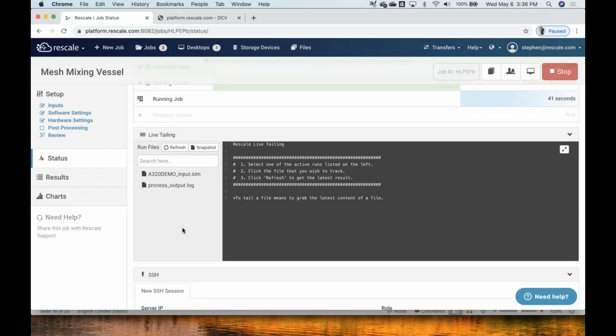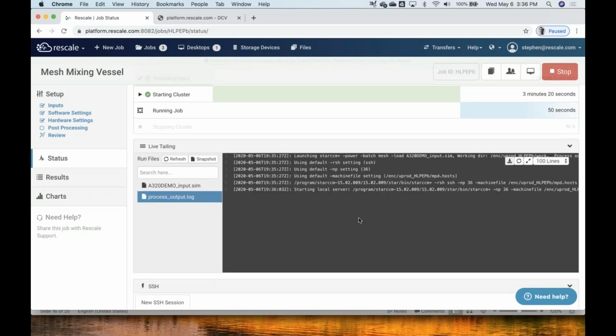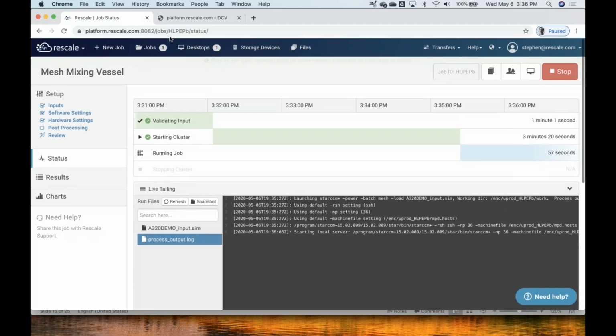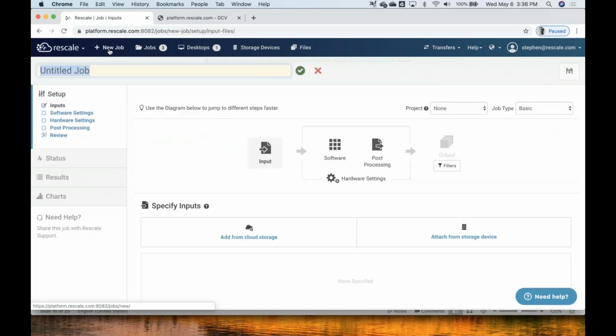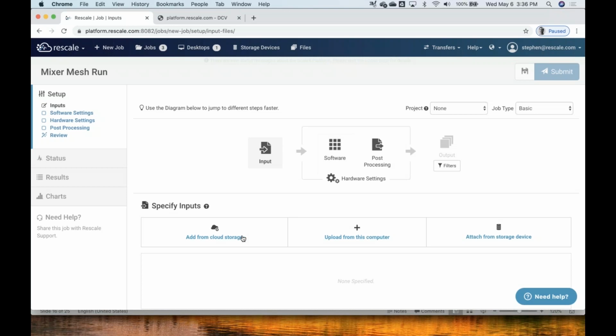And this is also where you can see one of the reasons why I wanted to output some of my plots and scenes automatically through STAR. We have the ability to look at that here as the solution starts converging, or in this case, meshing. We can see what's going on with the platform. So I wanted to show those two steps just to show you how to start building up the complexity of the platform. Now, I could do something, again, utilizing the tree and the automation of STAR-CCM+, I could do more than that, right? So we can start adding some complexity here.